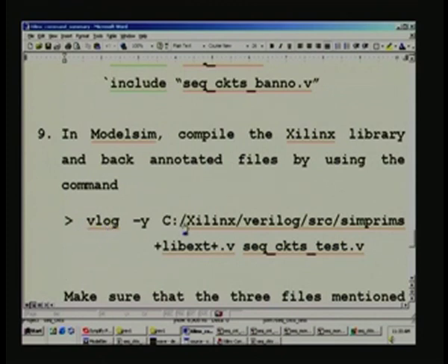and what we had to compile is the library file, because after back annotation you will get all the primitive cells coming into this file. So, basically the MUX, LUTs which I had told earlier, these primitive cells will get reflected into this file, and if you open out the back annotation you will precisely see this, and you have to compile that file.